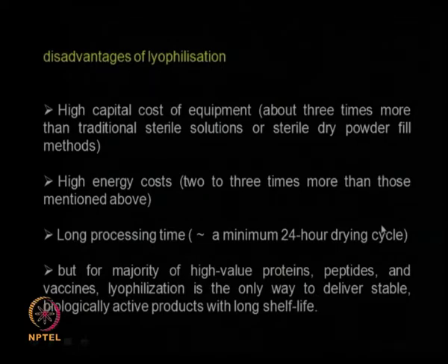If I am going for conventional drying where I apply vacuum and heat the material so that the water becomes vapor, I may finish in a few hours, whereas in lyophilization or freeze drying, where I freeze the material and then change the temperature and pressure to remove the moisture, it may take 24 to 48 hours.